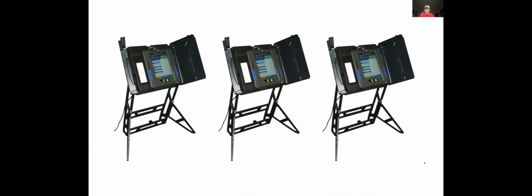So how do we deal with those? One of the most popular ways is having a voting system. So you have 2, 3, 4 computers that are running the same code with either the same sensors or a different matrix of sensors. So maybe it has a different magnetic field sensor, or a different accelerometer. And they're still making the same decisions. And then they would vote, like, oh, I think that we should do this. Well, if there's one odd one out, it's more probable that one is the broken one. So then that output would be ignored and the satellite would not do that decision.